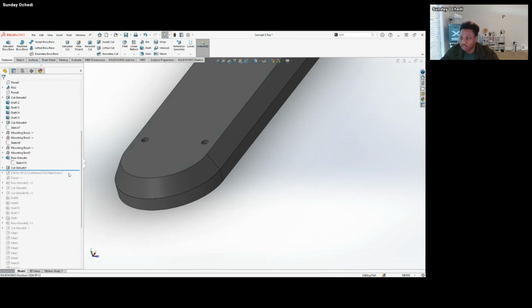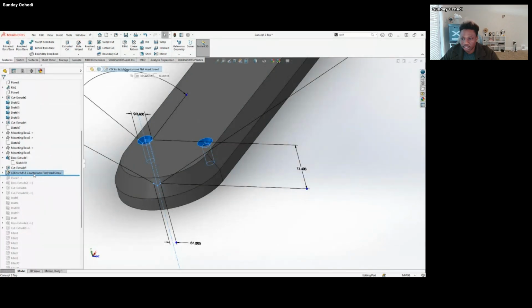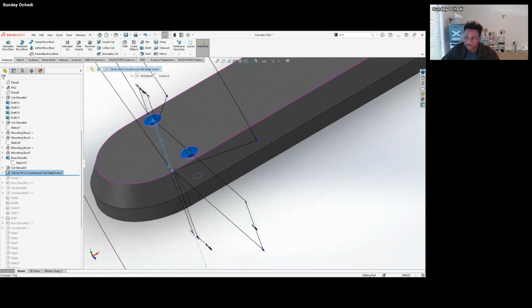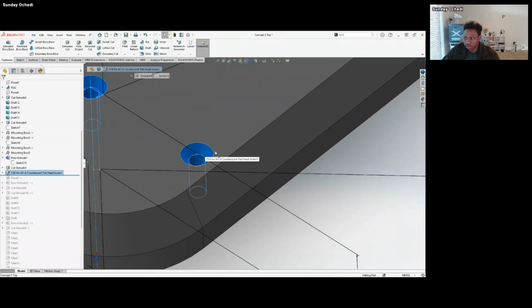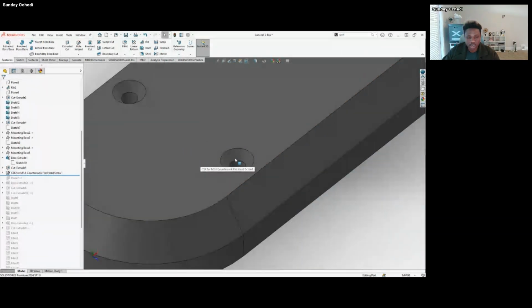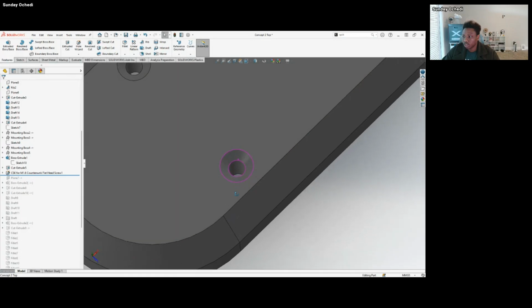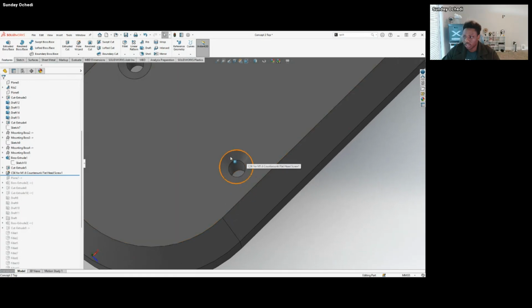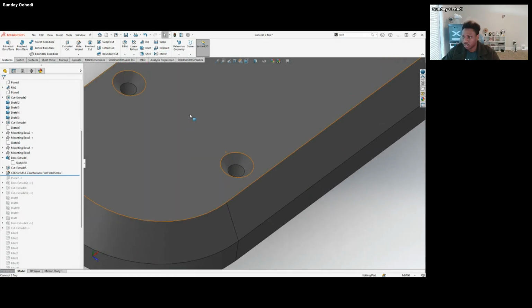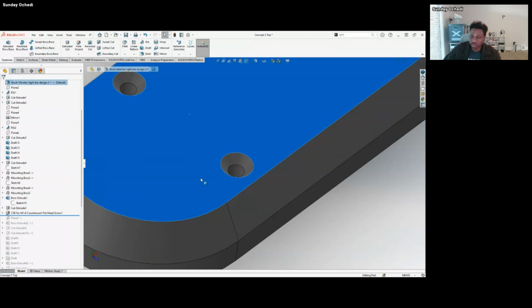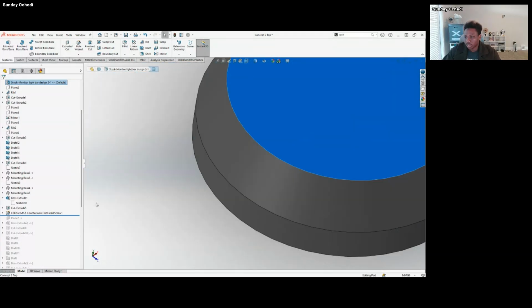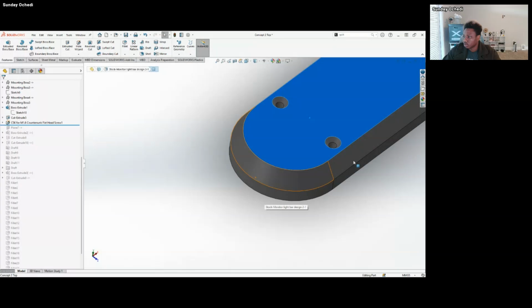And that's when you use your hole wizard and then select the countersunk flat screw, select the diameter you're trying to use. In my case, it's M1.6 because I want it to be small, and then it creates this. So this way, when you put in your screw, it gets flush with this surface, so you don't have anything protruding out. It helps with the aesthetic as well.